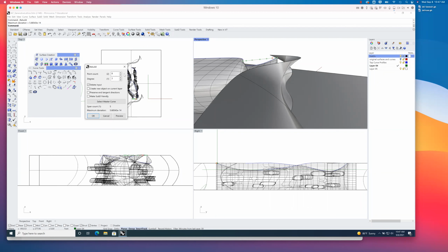I can change the point count, right, from 2 to something like 8. That'll give me a lot more points across. And then the degree of curvature, right? The first degree curve is what it is currently, which means it's just a straight line segment. If I change it to third degree, that's what I want. Then I can make it something nice and smooth like a spline. 8 points seems a bit extreme. Maybe I'll switch this to 4 or maybe even 3. Let's see. Yeah.